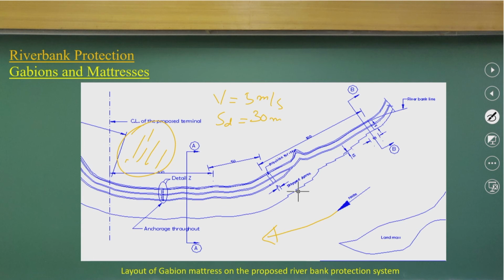River bank protection work for the Brahmaputra river, and you can see this plan view for the design velocity, and you can see there is an apron here, the stepped apron you put, and there is a tie concept, and there are different lengths, and if you look at this scouring stepwise apron, we have been propagating it. So, just follow all this, and this is the Gabion matrix that we have designed, and I am not discussing more detail.